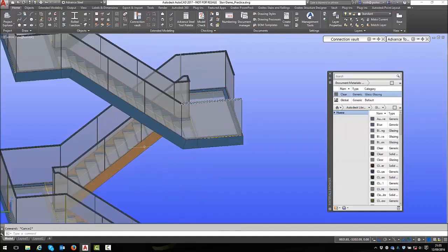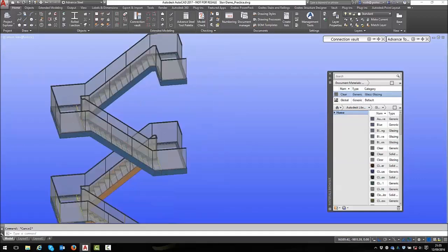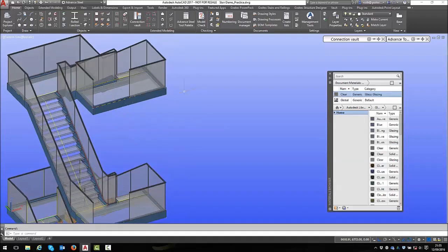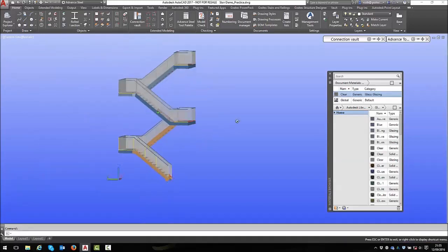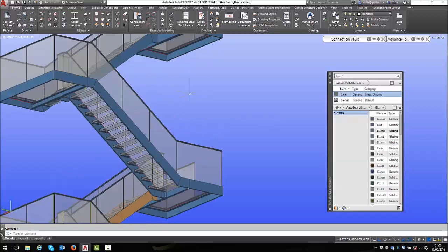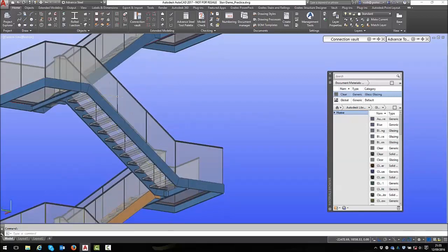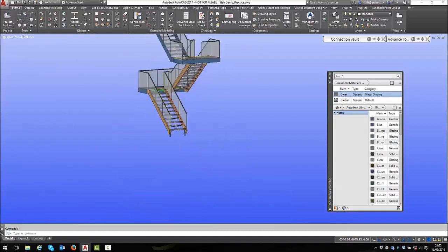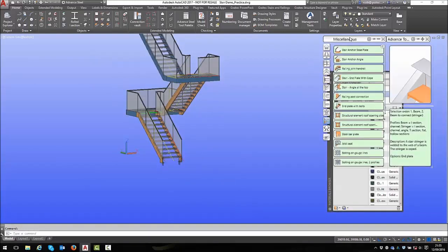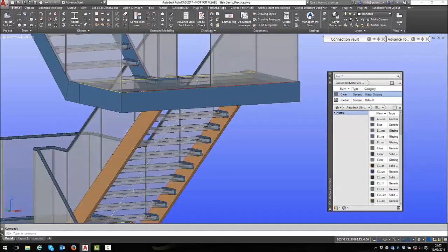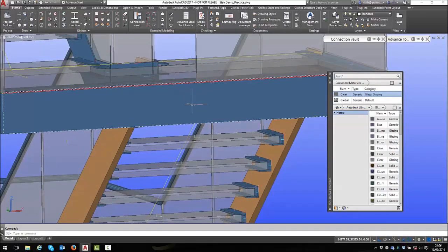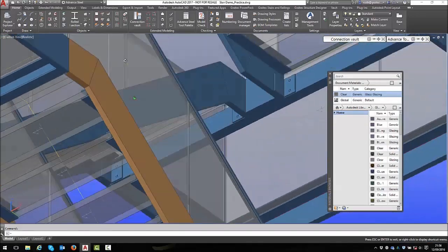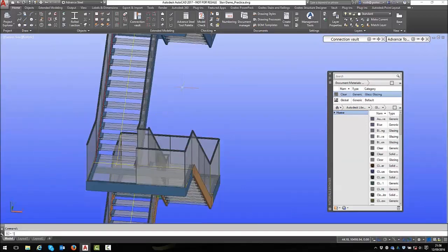Okay, but the process was exactly the same. I could take this and I could copy it and I could rotate it and copy and rotate. I've taken some glass panels there. Look, this would be the step offs to the doors, and this is what we got. So it's quite effective. I haven't put any joints in between the rail here. I have in the top section. Look, I didn't put them in the bottom section, but you can see that. There's actually tools for that. And I can't remember, I probably used this one, stair angle at the top. And I used those up in here, wherever it is, lost it. Okay, so that'll do.